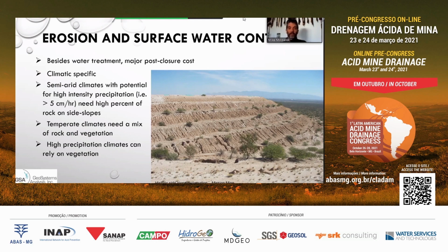And so it's quite important to consider the long term, and especially with surface water channels, you need to keep them clean. You need to keep the sediment out of them. Otherwise, the water will jump out and erode and destroy your cover.